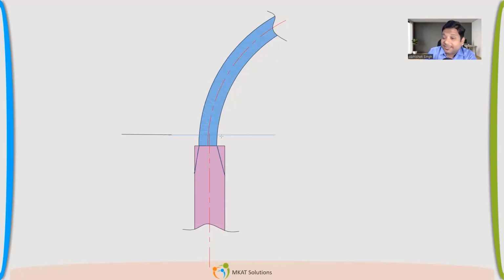And if it is a cylinder, the thickness requirement will be 18 or it will be 12. Can I have less than 18? If 18 is my nominal thickness, can I have less than that? You will say, oh, I can go up to design, but you have to match with 12. And see, the dish end is having a little bit of straight face, which is 12 thick.